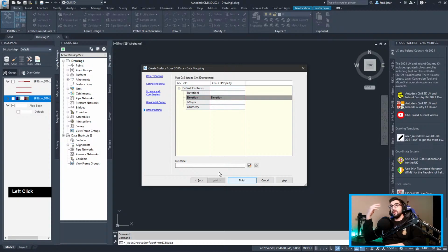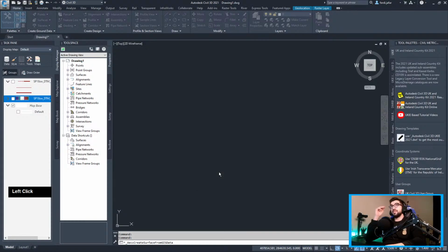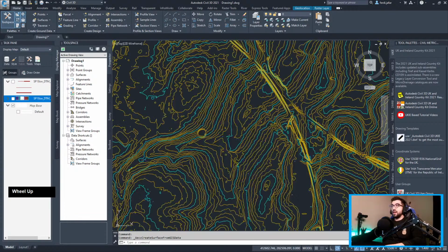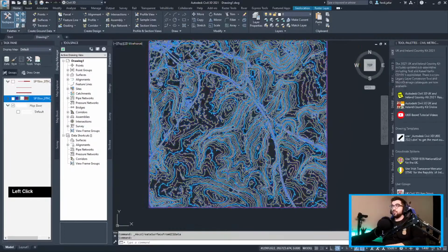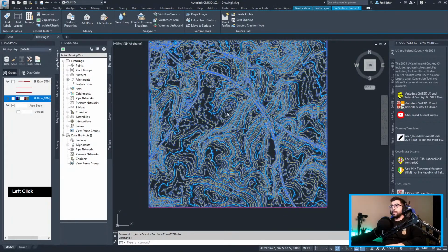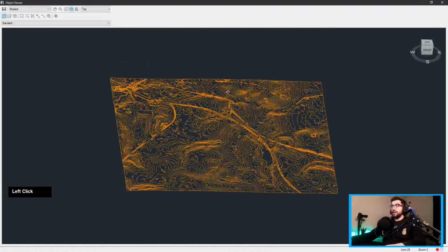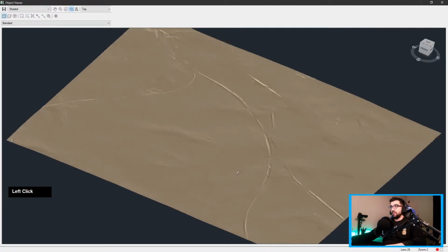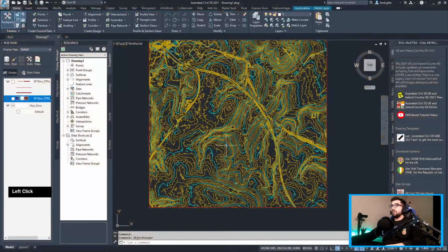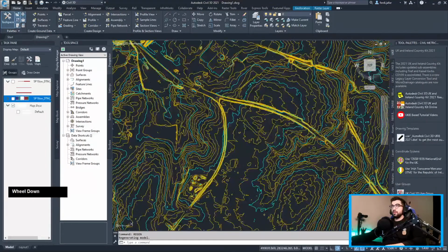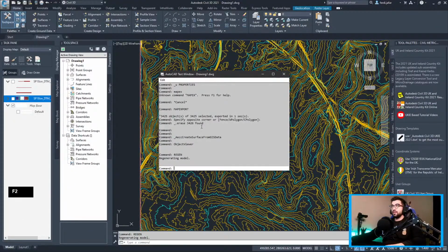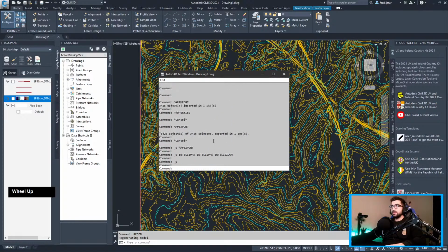so we can actually create the surface model from the shapefile that we have exported. So basically, we import the TIF, we export contours, we import the contours back, and then we export them as shapefile. And now, as you can see here, this is a surface model of the TIF. Now, there must be a way that we could see, as you can see, that's the model as well. So that's how the ground is and everything. Now, where did we show our proposed, where is our, we deleted our, there we go. No, actually, where is it?